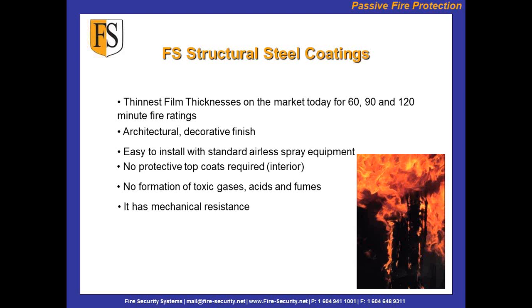Otherwise, if you've got a very small section and you're only putting 0.5 millimeter of fire protective coating on it, it's not going to do the job. It's not thick enough to stop that steel section from losing integrity.